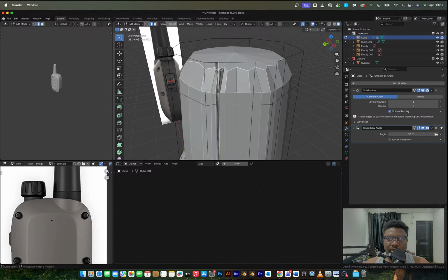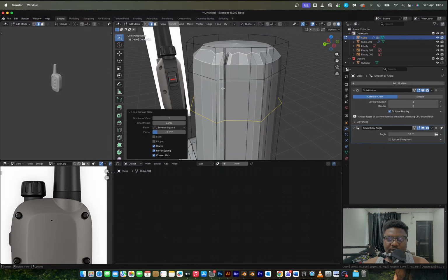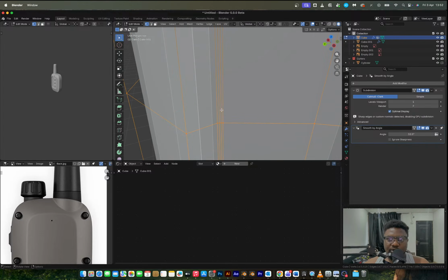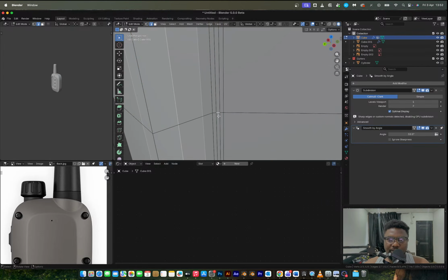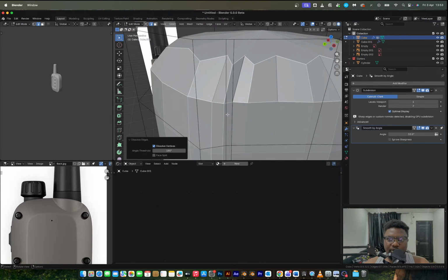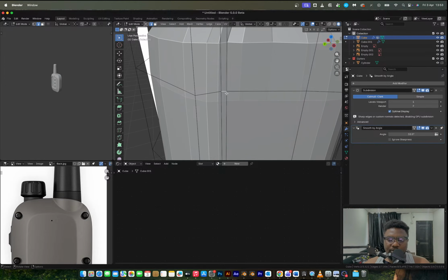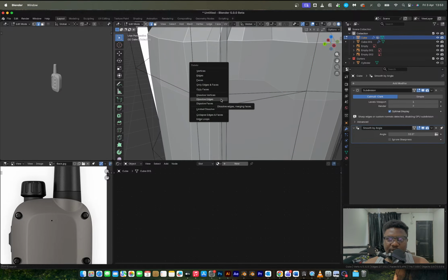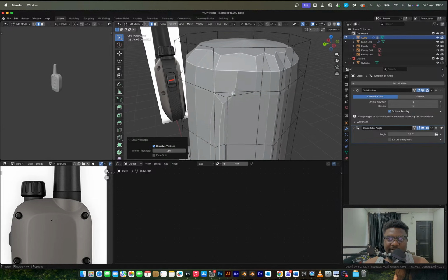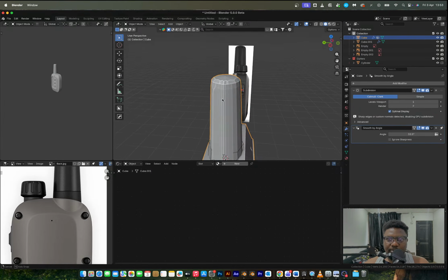What about if I dissolve some of this, maybe terminate that loop around this area. So it's going to be something like this, GG. This terminates here. I can join these two, select these two, dissolve that edge. Then we officially have only one going up to the top. Then when we get here, we'll do the same operation again. Select these two, join. And then these two are going to be dissolved edges and we have nothing getting to the top.